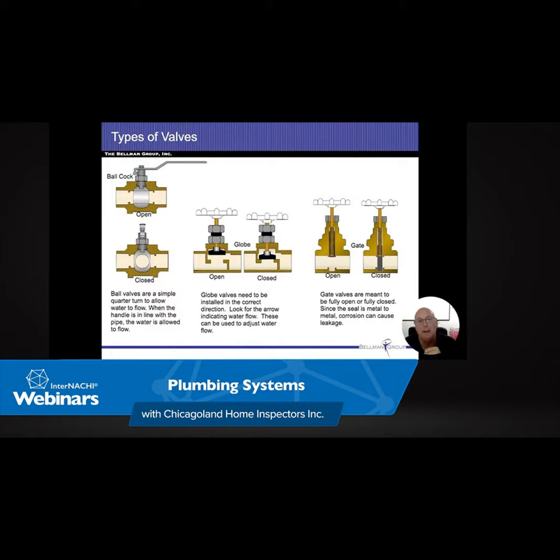All right. If I go back a slide, those holes that are on the left and right, that's where my combustion air goes in. And as it goes in, it goes to the top of the tank. Or I should say top of the vessel. And then it comes over an edge. And then it comes back into where the burner needs it for the combustion air. This is supposed to stop any gas fumes or anything else from being able to get to the fire and causing an explosion or a flame on there.